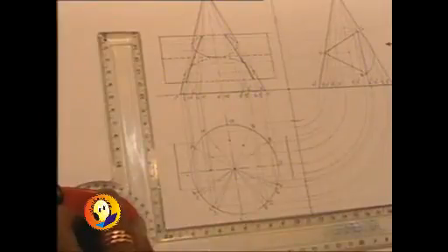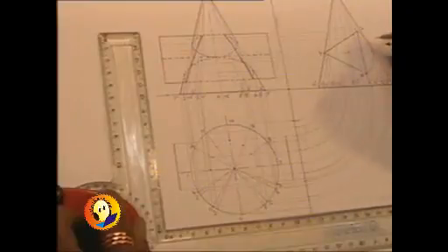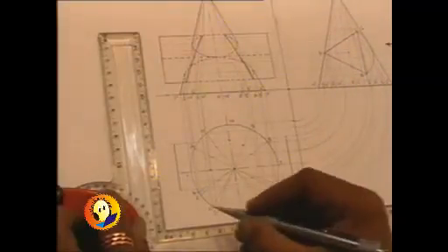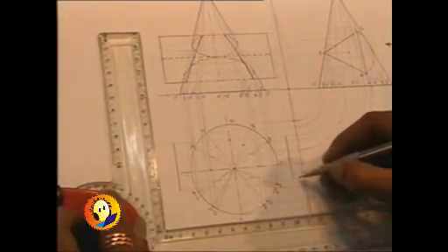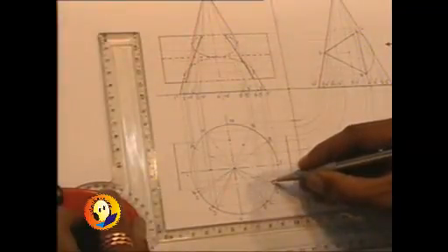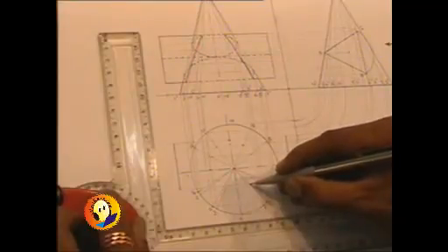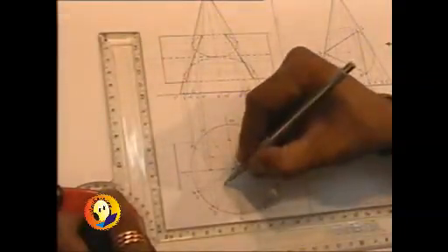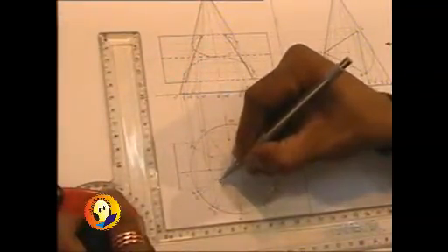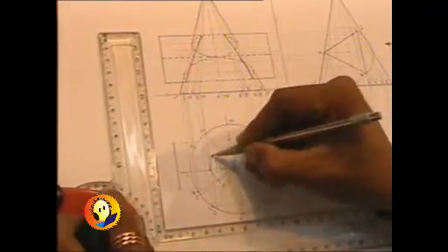And then finally the point on generator C, which will be the topmost point. In this case it is generator C coinciding with generator B. So this is the point which will lie on the generator through C. So you get these 2 points, and this is the curve which is to be drawn fully to complete the top view.